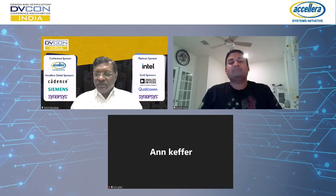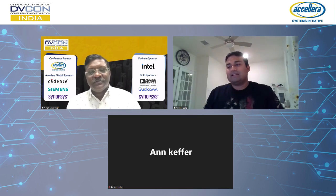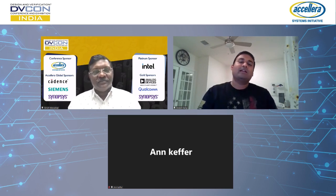Thanks, Vedant. There's one question from my side, from my education. You're talking about the fault campaign, and you're talking about the injection and classification. There you use a term called software known answer test. May I know a little more about that? Sure. So a software known answer test is very similar to a software test library. A known answer test, the name comes from the fact that we have done a golden simulation and we know what the initial vectors are and what the known state of those initial vectors is.